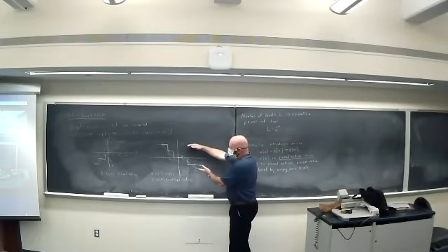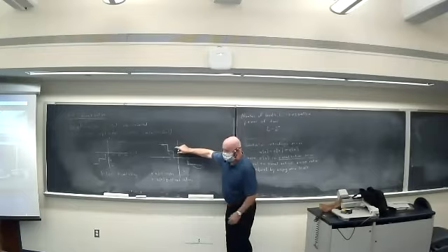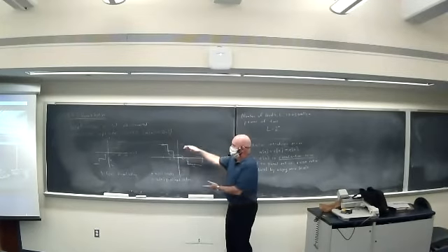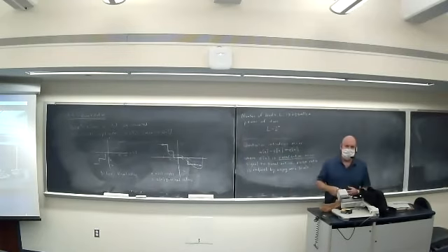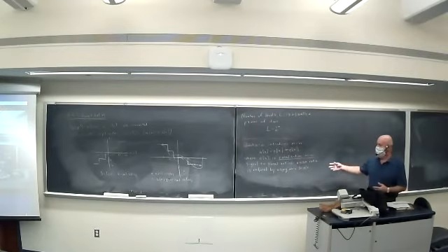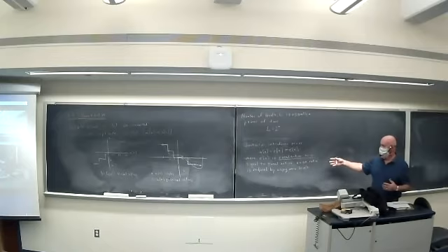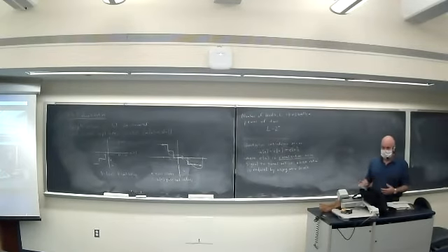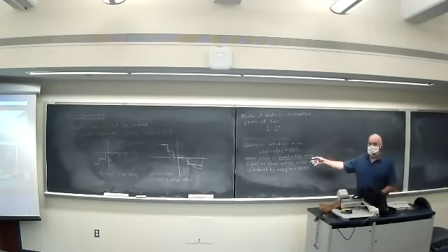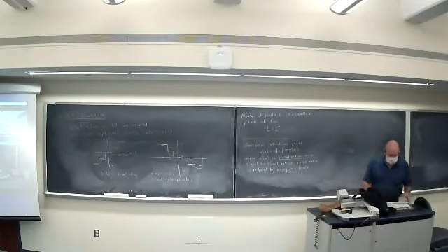Here, if I've got 5 levels between -2 and 2, I'm probably getting half a volt of error. If I've got 256 different levels though, my error is going to be considerably smaller over that same range. So one of the things we'll come up with in this chapter is a formula for the signal to quantization noise. Now this is always going to be present, and it's not the same as external noise, right? This is deliberately introduced in the sampling process.